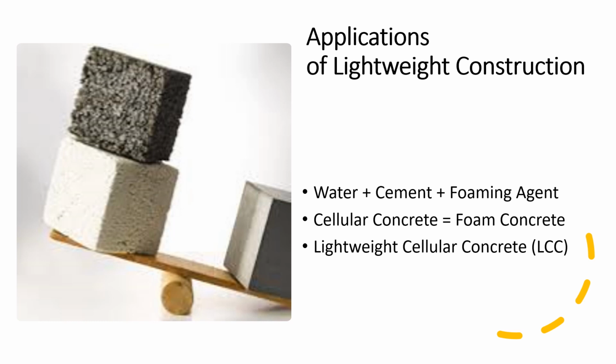As we know, cellular and foam concrete are two names commonly used interchangeably when referring to lightweight construction. Some studies call it LCC, which is short for lightweight cellular concrete. Cellular or foam concrete comprises lightweight components such as cement, water, and a foaming agent, and in some cases, lightweight aggregates. The foaming agent traps bubbles or voids in the concrete, giving it lightweight properties.